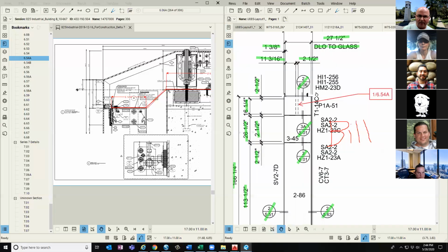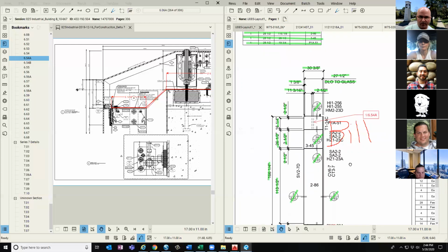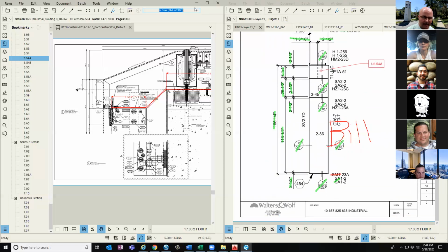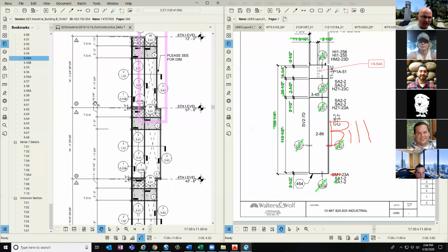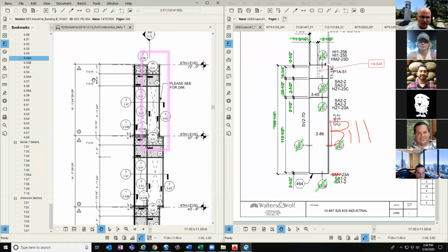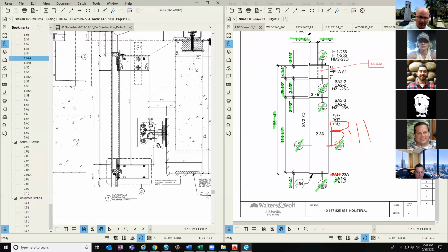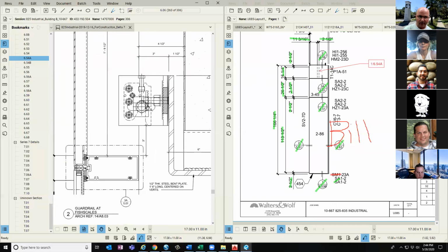So after that, we're going to start looking at what's happening on the verticals. Vertically, if I go back to my elevations, I see that I have a wind load condition at the sill, and I've got a dead load condition above. Well, I've looked at my horizontal details, so I recognize that my dead load is going to be on this hook lug. We already talked about how the pony tube is set up. So when I get to the pony tube, I'll be able to do some verifications there as well.